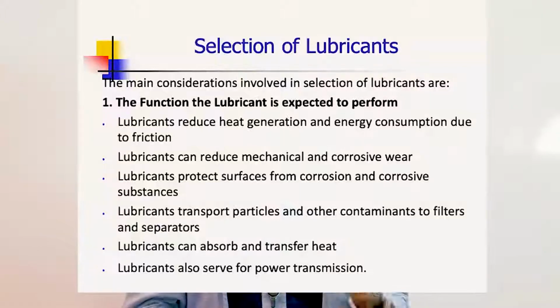The first thing is, I should look at the function that the lubricant is expected to perform. That's the first factor that comes to mind. What is the function that this particular lubricant I am looking for is expected to perform? Lubricants reduce heat generation and energy consumption due to friction. Lubricants can reduce mechanical and corrosive wear. Lubricants protect surfaces from corrosion and corrosive substances. Lubricants transport particles and other contaminants to filters and separators. Lubricants can absorb and transfer heat. And then lubricants can serve for power transmission. All these are the functions that a good lubricant is meant to perform.